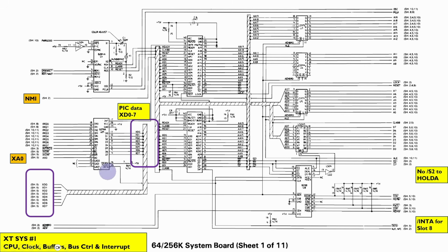So then the XT, you'll notice that for this, the interrupt controller is now connected to the X bus here, the X data bus, not directly to the AD bus, the multiplexed bus here. And you can see this diagram probably isn't quite as clear. It almost looks like it was hand-drawn, but we've also got the clock controller, bus controller, coprocessor, and again we've got our various buffers and latches in here.